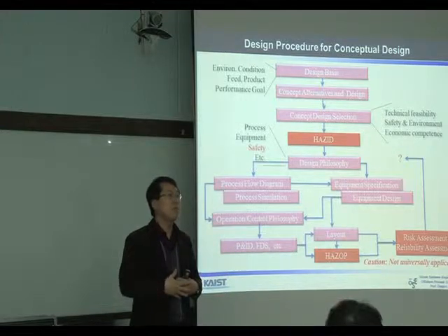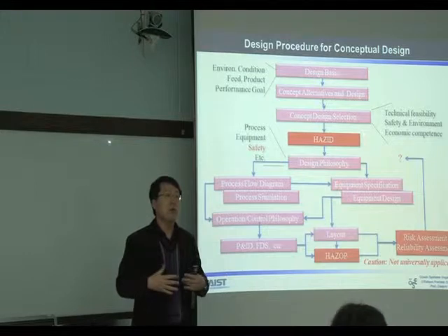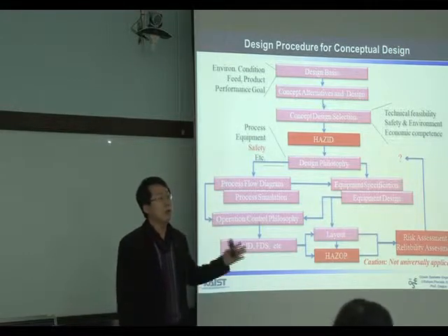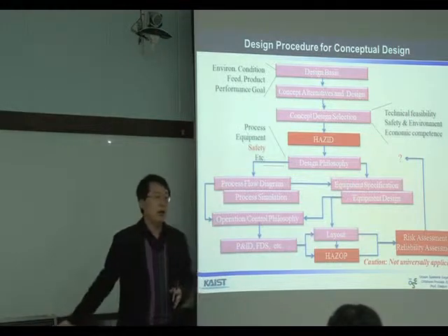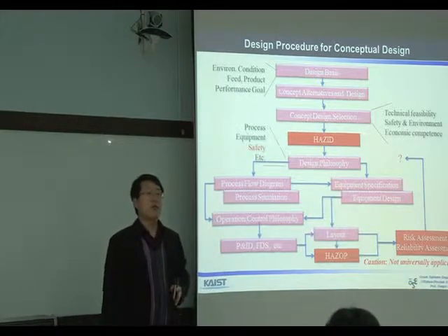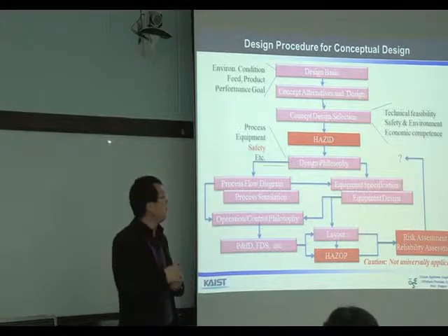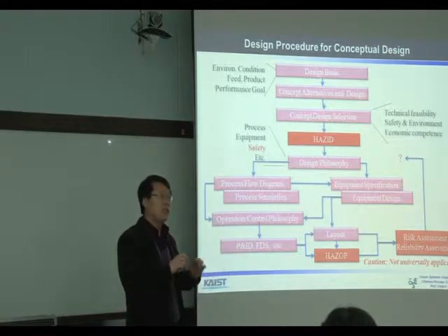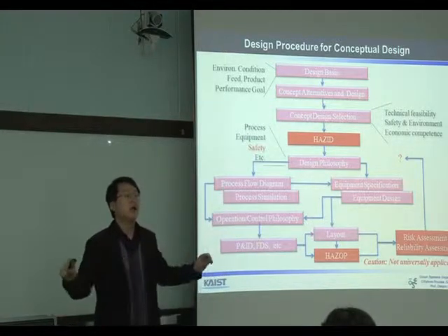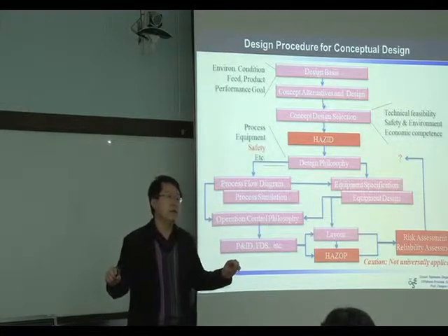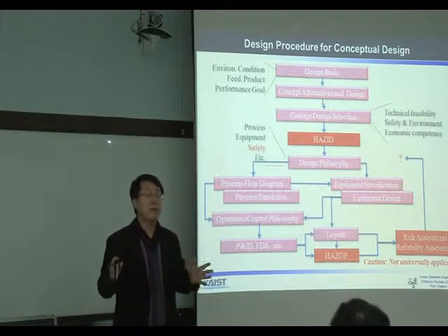For example, the heat exchanger designer needs information about the incoming flow rate, temperature, and pressure, and the outgoing pressure, temperature, and flow rate. Based on that information, the heat exchanger designer can develop the detailed features of the heat exchanger, the number of tubes and the internal baffles.